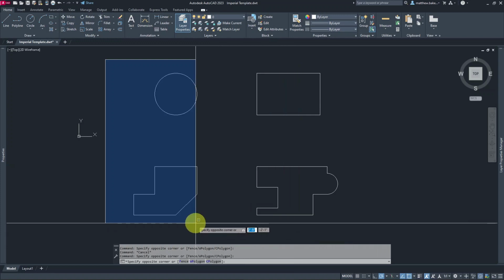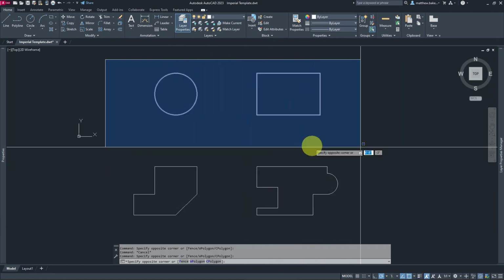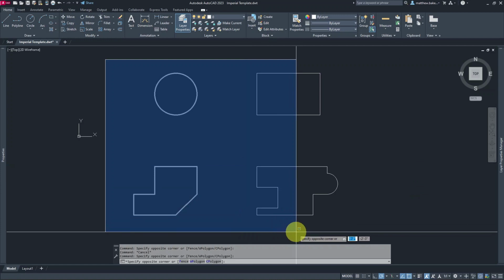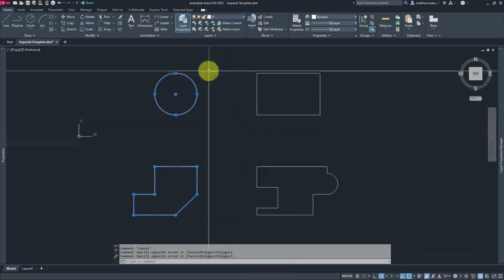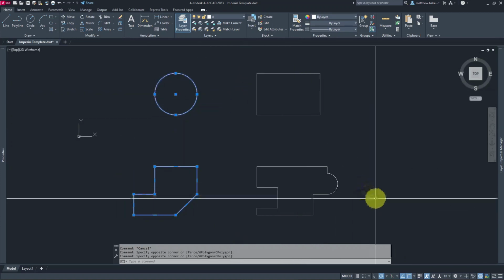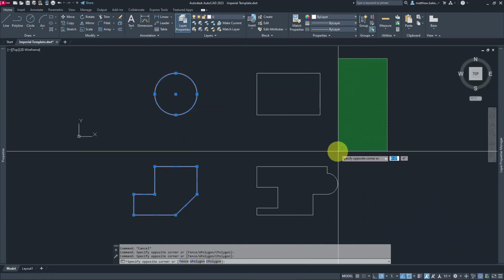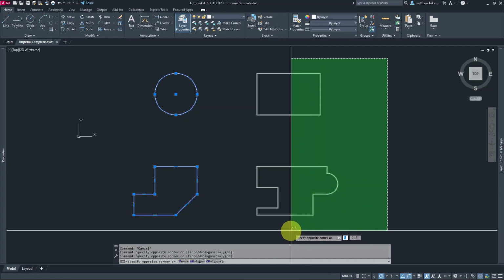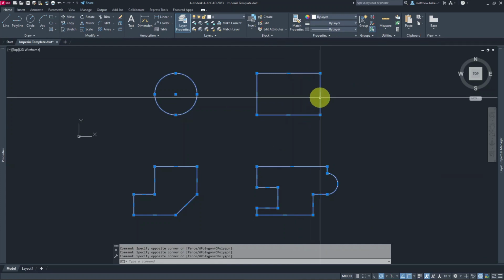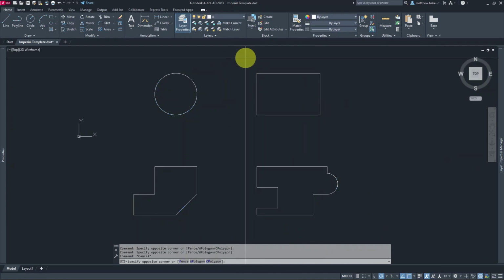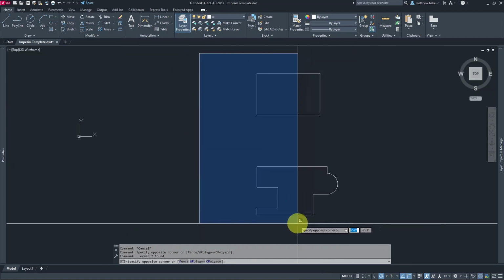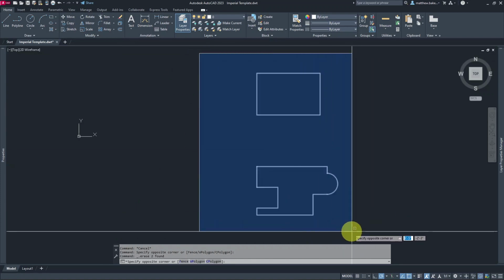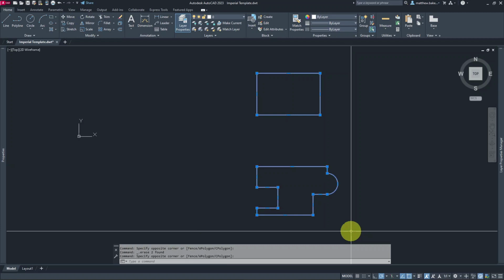So let's say we want to delete these first two, pretending all these objects are a little bit closer together. So we'll do the second click here. It will only pick these first two because we didn't completely envelope these ones. But again, with the green, same thing. We're only clicking over half. It'll select the entire object. So let's just delete that. And again, instead of like this, we'll envelope the entire object with the fence and hit delete.